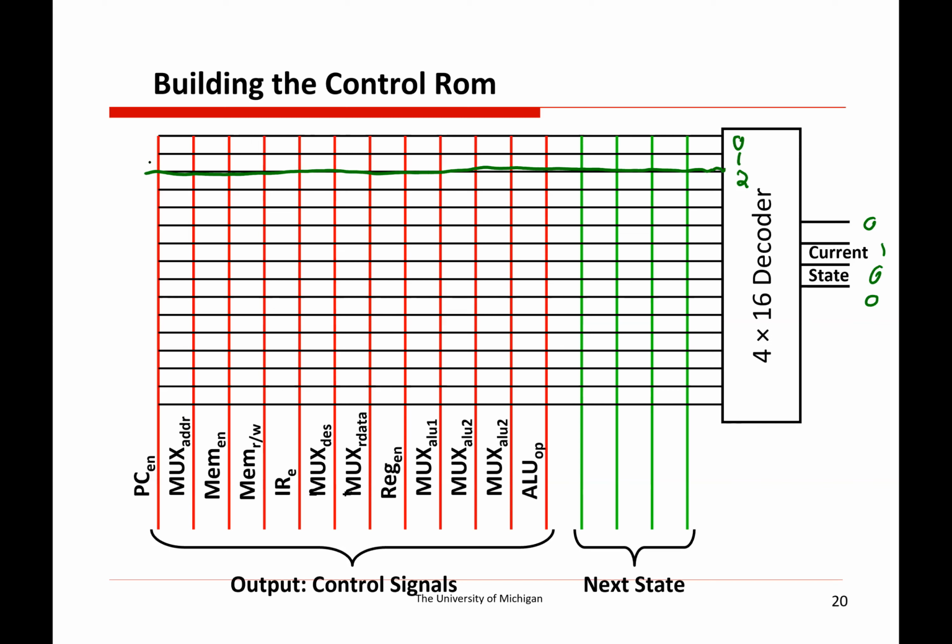And then we can program what the output is by putting little diodes in here, such that if I set this to 1 and this to 1 and then leave all the other ones not connected, then this ends up reading out 0, 1, 0, 1, 0, 0, 0, 0, 0, 0, 0. We're going to use this illustration as a way to show how we're programming this ROM.